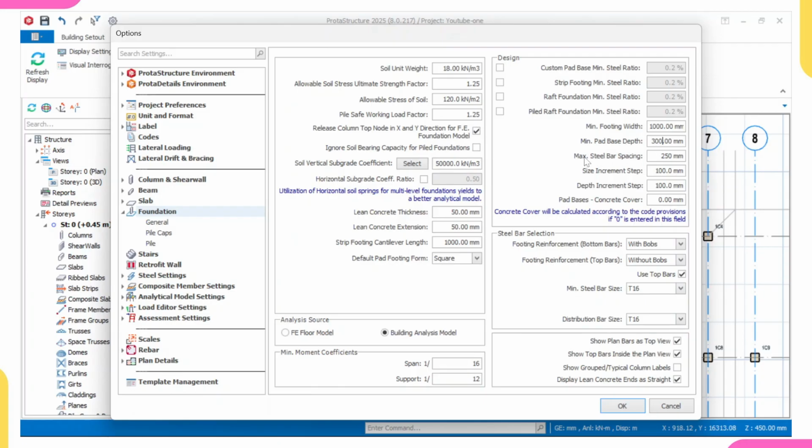Then coming over to maximum steel bar spacing, I'll leave it at 250. But remember what I told you, that even in footing, because of quality, I always like to go with a spacing of 200. For that, I know that 250 will pass. In fact, let me just leave it at 250. Then during detailing, I will now use a spacing of 200.